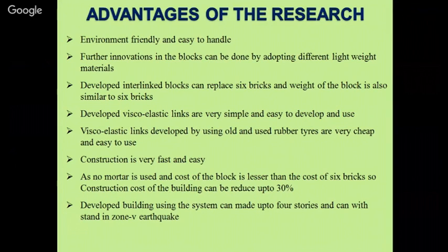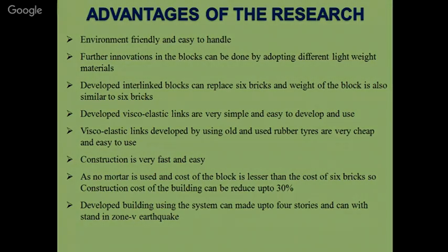You can construct it at a very fast rate, and how is the cost of construction reduced? You have reduced the cost of the brick, the cost of the block, and you are not using any mortar. Only plastering is done after your construction. And another thing, you are not providing any vertical and horizontal reinforcement, so the reinforcement cost is curtailed. Then your workmanship cost, your labor cost, also reduces.